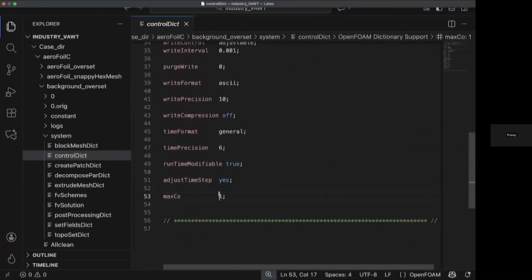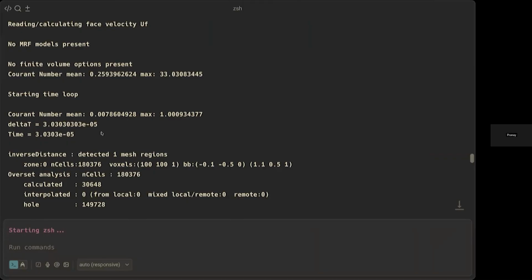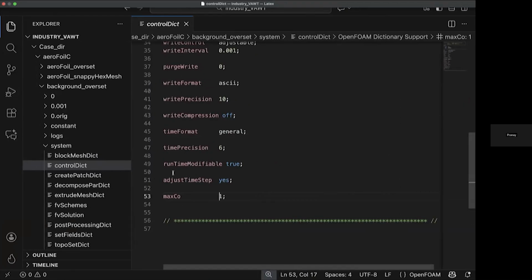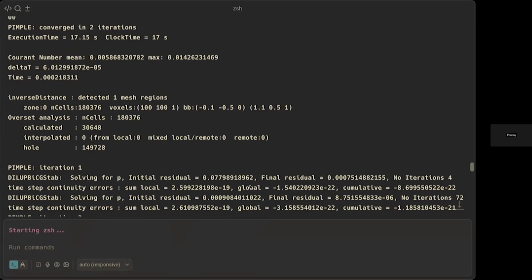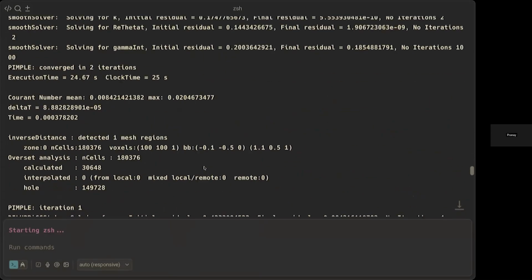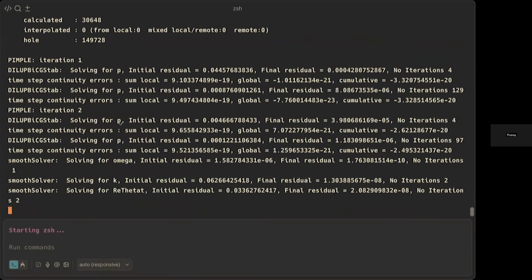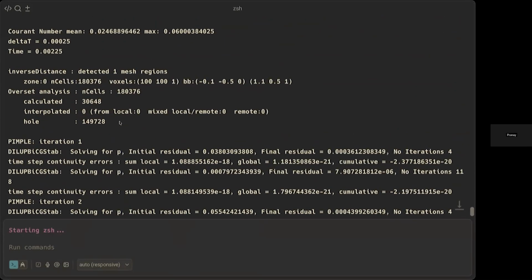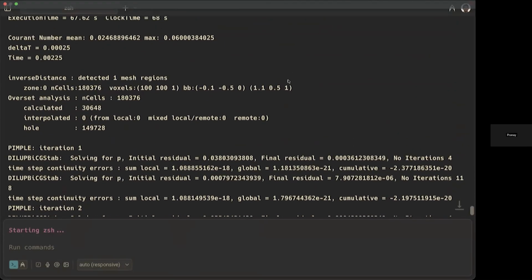Had it been 0.1, you could expect a reduction in order by 2. Right now it is 10 raised to minus 5, and you could see 10 raised to minus 7 also to account for this CFL, where maxCo stands for max Courant number. So the solver will keep on iterating until the end time. This is usually how the terminal looks when the case has been resolved.